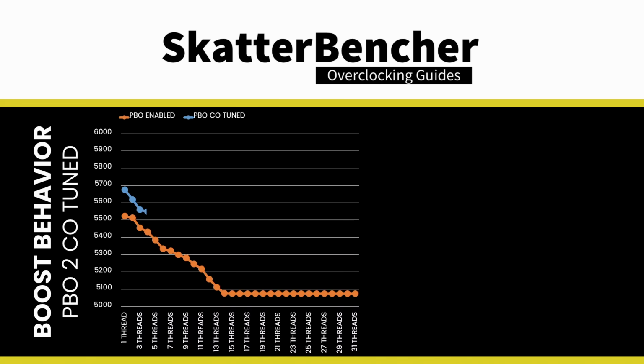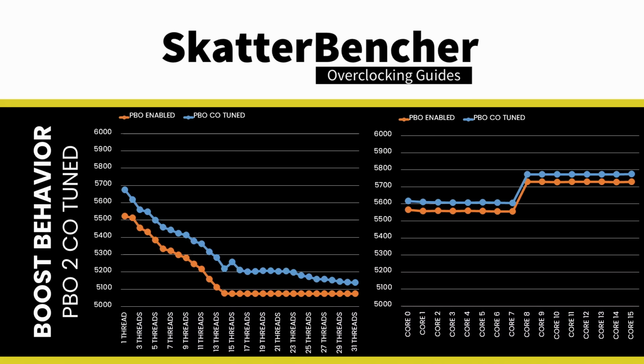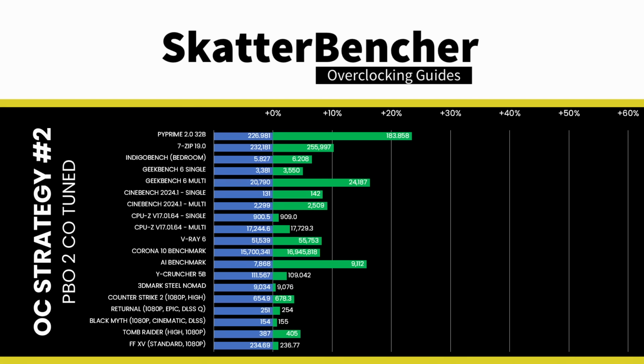the boost frequency at one active thread is about 5675 MHz, and the average boost frequency gradually trails off to 5138 MHz when all cores are active. In light, single-threaded workloads, all cores in CCD0 can boost to over 5.6 GHz, and all cores in CCD1 boost to about 5775 MHz. We reran the benchmarks and checked the performance increase compared to the default operation.